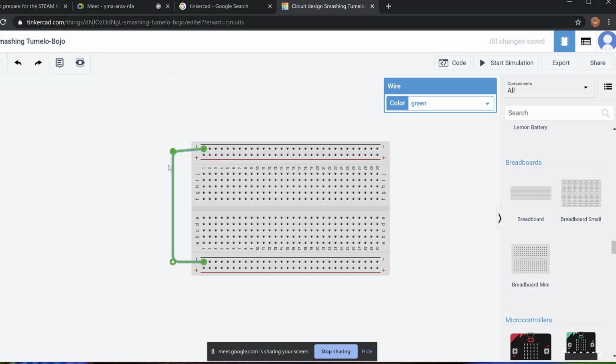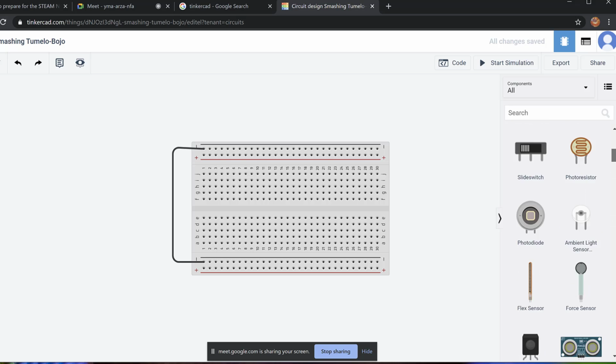And then you can adjust. You see, whenever there is this node or circle, you can click on it and drag it to adjust to wherever you want to have it. And you can also change its property. The property is the color. I can make it, let's say, black, because normally the blue line here is for ground. Okay, and I'll explain what ground is and what negative and positive are. So for now, we are just getting familiar with the tool itself, Tinkercad. Okay. So now I want you to go and grab a resistor.